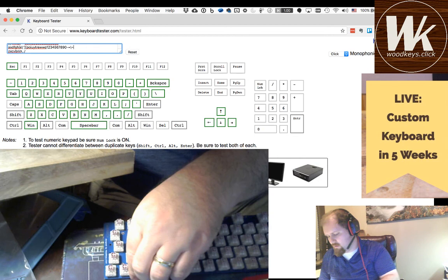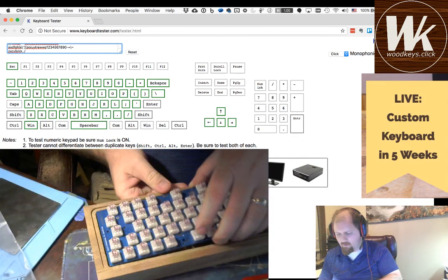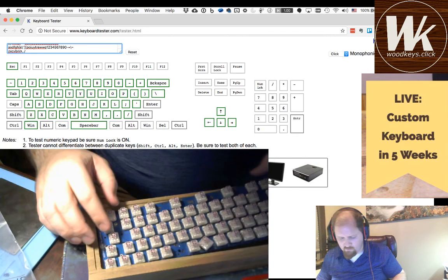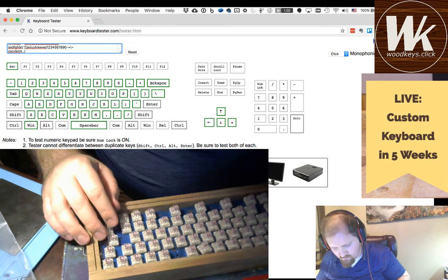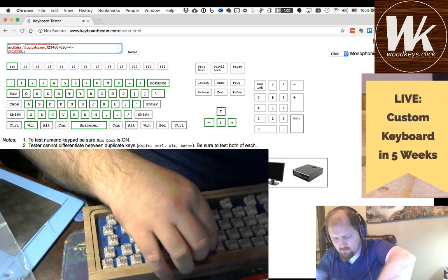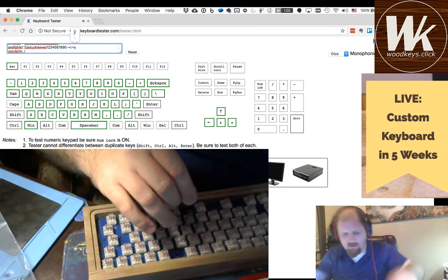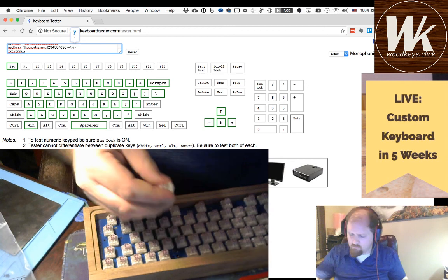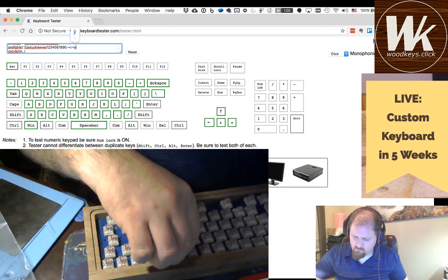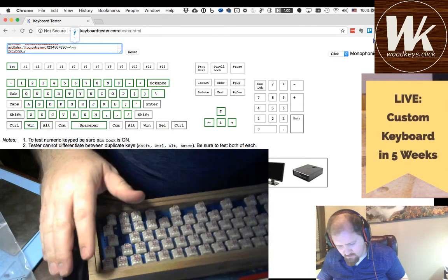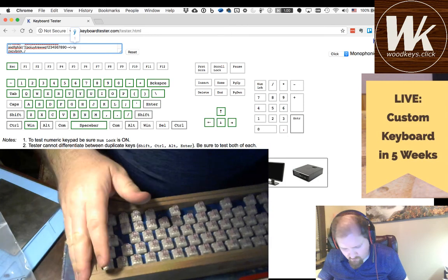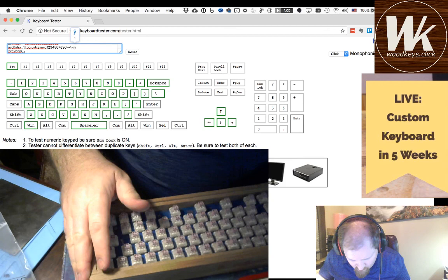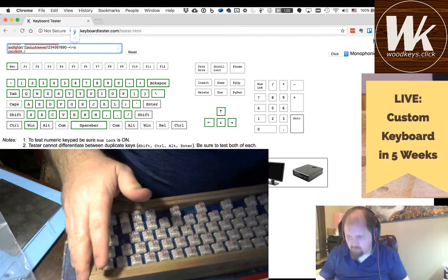But it does fit in here. Those switches do not stay in without PCB mount pins, by the way, so that's a good lesson to learn. Don't try to do this without a plate, oops, and without PCB mount pins. Just to show you that this does, in fact, work. It needs the spacers to fit quite right, but ta-da!